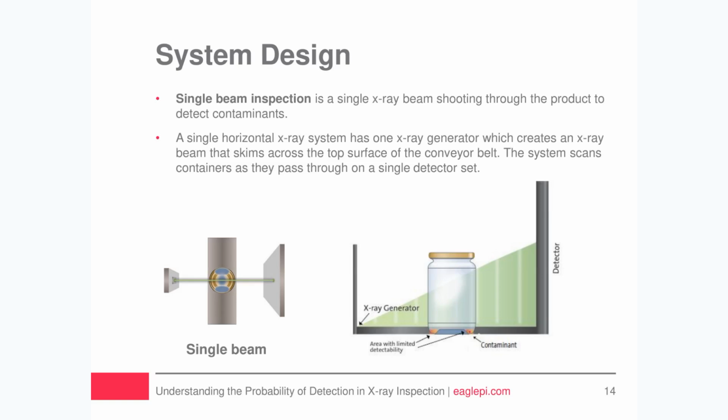As you can see in the above illustration, there are two areas highlighted in orange within the glass jar where contaminant detection is severely hindered due to the geometry of that jar. This is typically due to the large amount of material present, causing a much darker area within the image, causing less contrast for any foreign materials that may be present in those two regions.